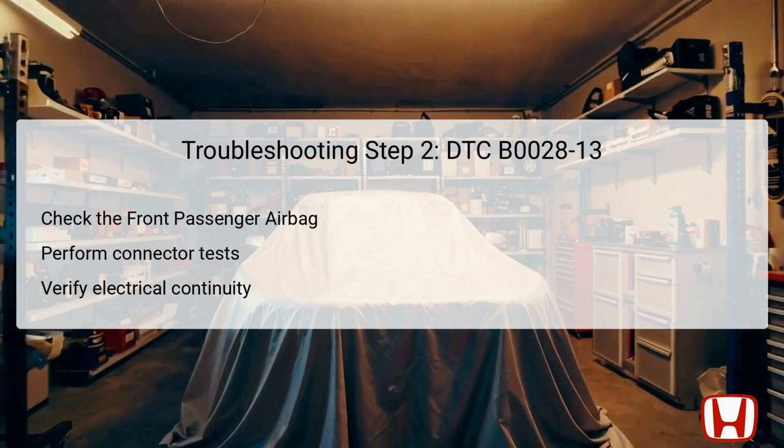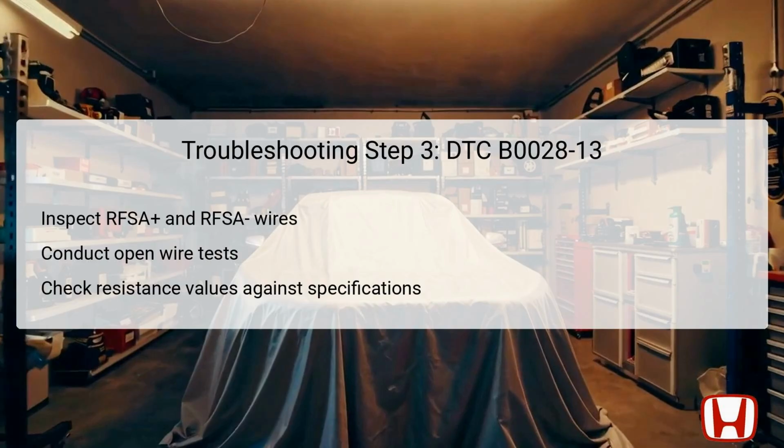Afterward, perform the confirmation procedure by turning the vehicle to the on mode and allowing for a wait period of at least 10 seconds. If DTC B0028-13 does not reappear after completing these actions, it indicates that the airbag itself may be faulty. If the DTC persists, the issue is likely elsewhere in the connected circuitry or the SRS unit, guiding the next steps of the diagnosis.